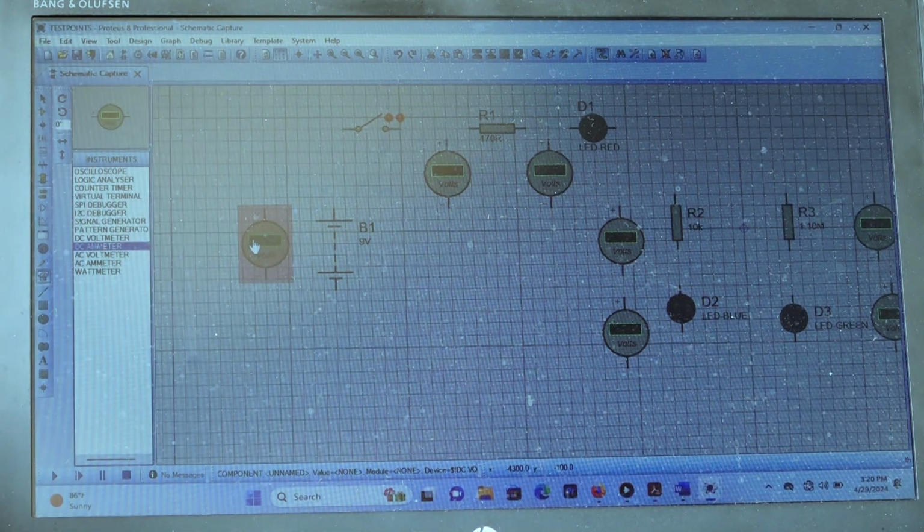We'll place a DC ammeter, but we have to change the configuration to have a DC milliammeter. Why DC milliammeter? Because once I have a resistance of 1.1 mega ohm, I know that the current flowing through that network will be very, very small. An ammeter cannot measure it. Are we together? Every choice of instrument should have a logic and reasons in your mind.